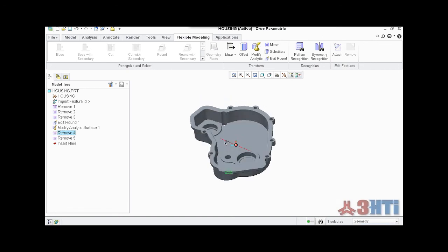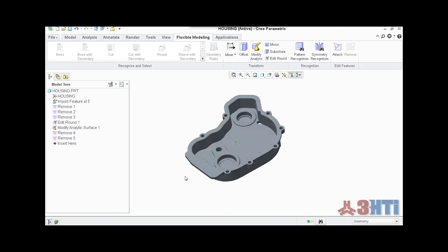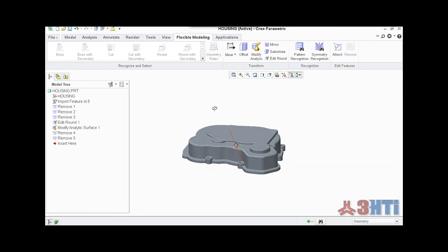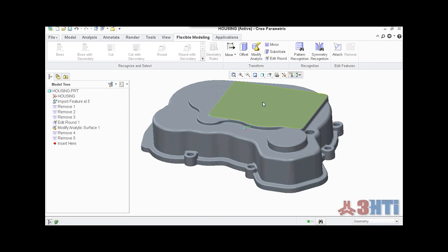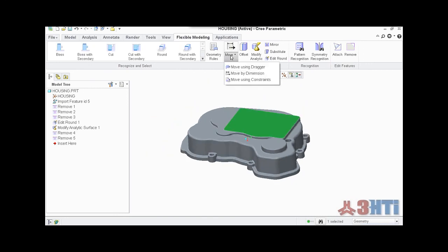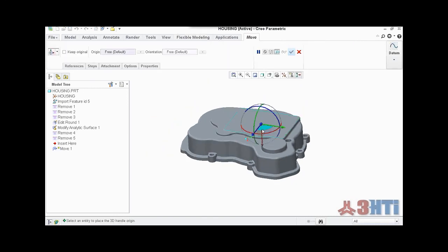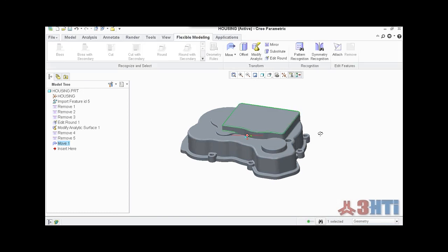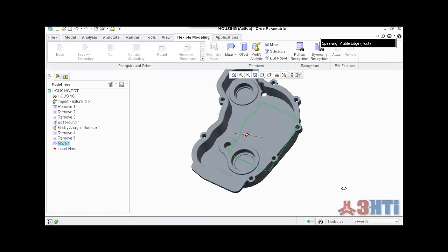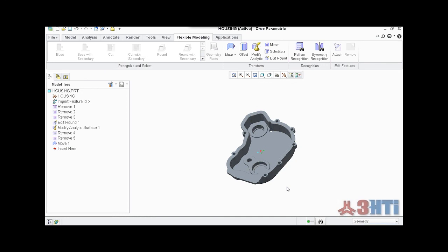Just like with the other models, like I mentioned, I made some design changes. I made some things parametric. I can do the same thing here. For example, maybe one of my analysis scenarios is, what if I make this a little higher? I can perform a move command to make this a little higher. I'm just physically kind of dragging that up a little bit. Okay, so the idea here is I took a model, and for FEA, I removed some geometry, and I put some smarts into some of the geometry for performing whatever analysis I need to perform.